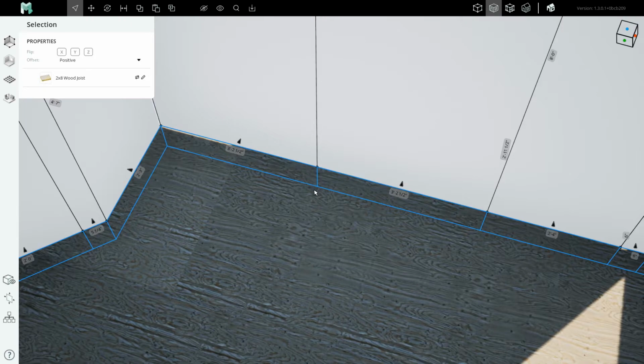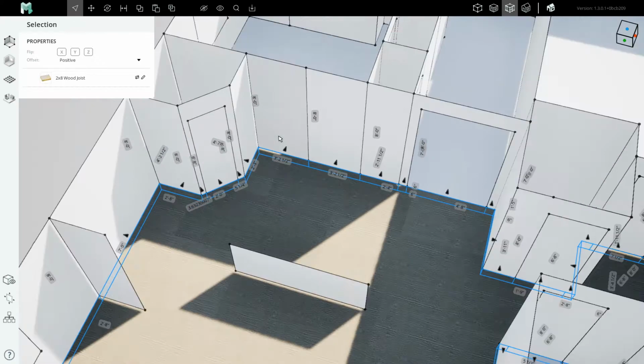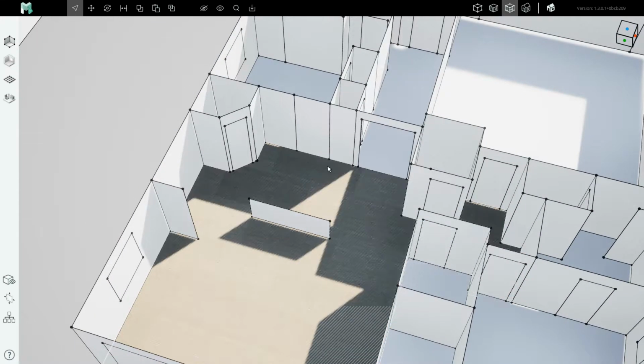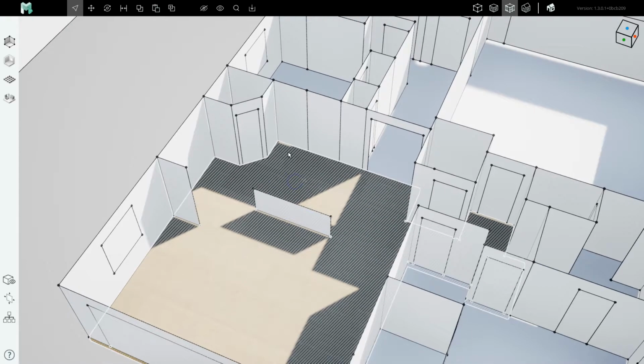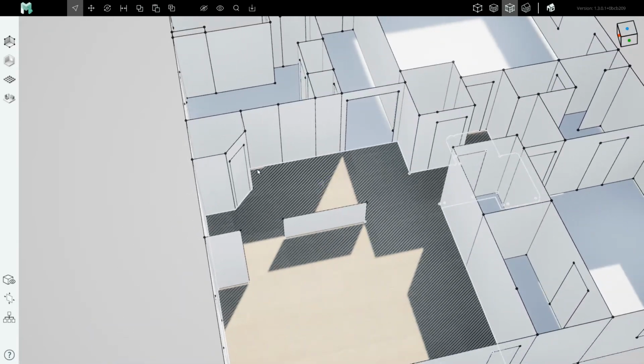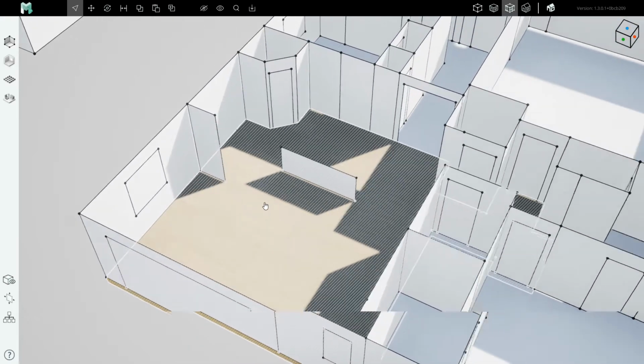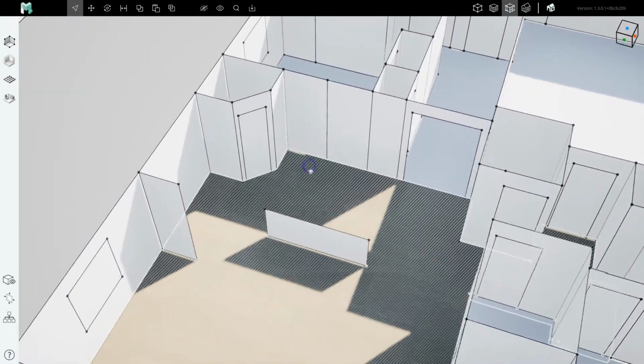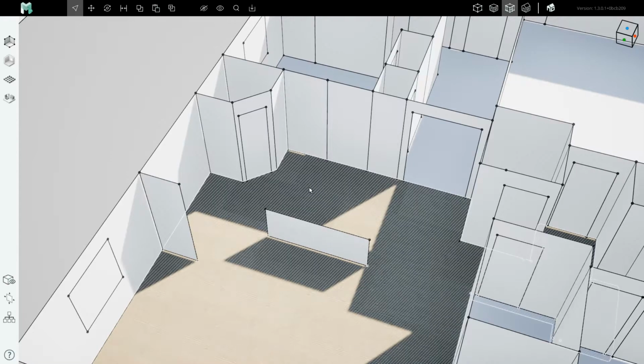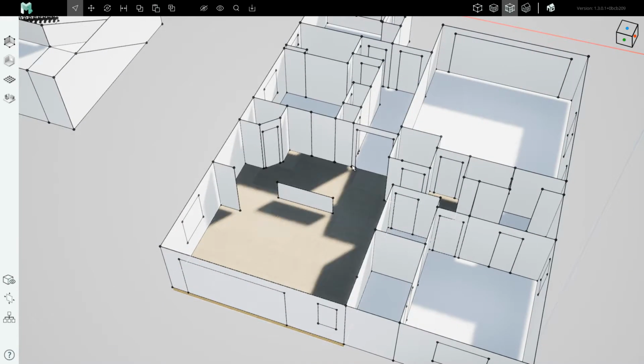That new blue line has just emerged, which causes the surface graph on which the cabinet was drawn to fall off. The surface graph, whenever the number of points around its perimeter changes, it sheds and needs to be drawn anew. So cabinets can tend to fall off when you make significant changes.